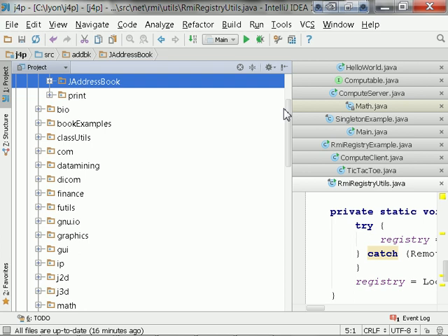So COM ports, serial ports in general, are an absolute circus. A 3-ring circus with clowns. And you can find them in 15-pin D-connects. You can find them in 25-pin D-connects. You can find them in circular 8-pin D-connects. And you know where you find them most commonly in circular 8-pin D-connects? Roomba robots. They all have RS-232 or RS-422 interfaces with circular 8-pin D-connects.